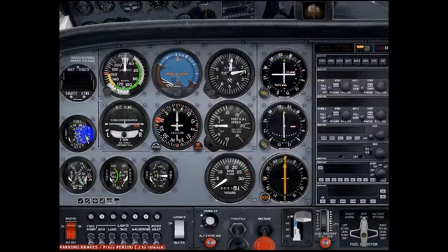So we have our fuel tanks. We have a left fuel tank, right fuel tank. EGT, fuel flow, we'll cover that later, but oil temperature and pressure need to be in the green. The vacuum system has a suction gauge, this is called a suction gauge. We have a vacuum system that applies a vacuum for these gyroscopic instruments, and it needs to be in the green arc. Then we have an ammeter here that gives us our electrical information and lets us know what's going on with the system electrically, to make sure all the electrical components are going to be okay.